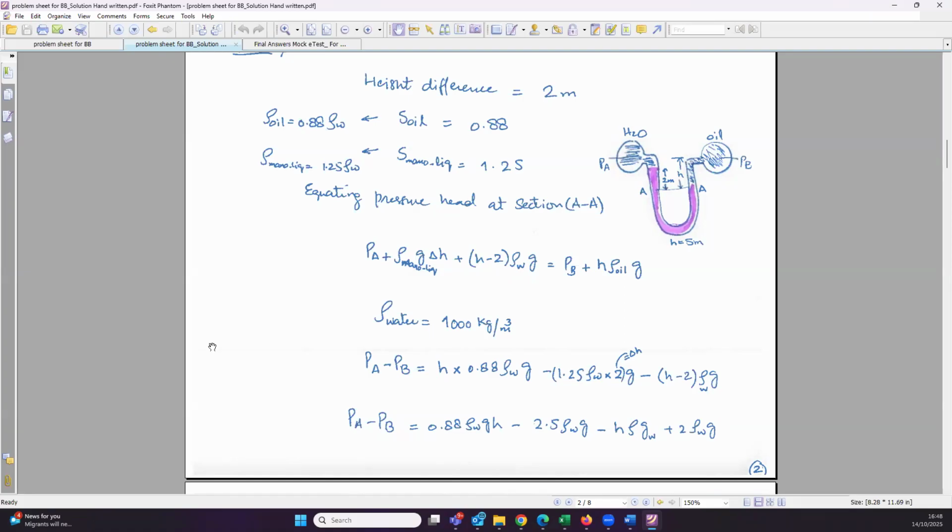If you increase the atmospheric pressure, you will see a smaller value on the gauge, because the reference you are measuring against has increased, so now it shows less pressure. While if you release the atmospheric pressure and go into vacuum, your gauge pressure will show a higher value, because now you have less counter effect from the atmospheric pressure. So think about what this reference and counter mean.